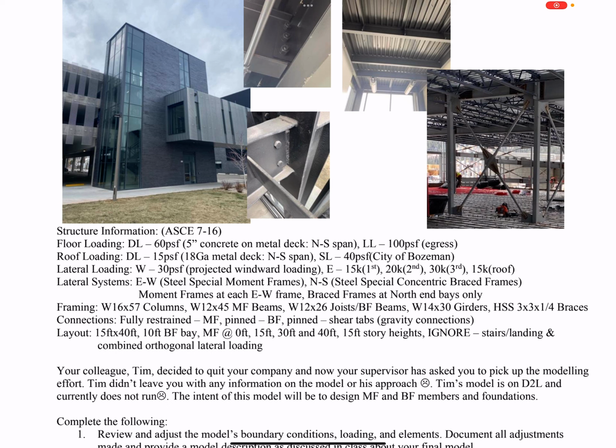I gave you the joist size and the beams that you should have for the brace frames. If it acts as a girder, I've got a W14 by 30 girders. HSS 3 by 3 by quarter braces.